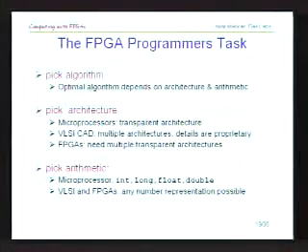You can have any number of bits for any variable, which is at first a little bit difficult to grasp, because you're used to having 16-bit integers, and we got used to thinking, well, we'll just pick whatever bit we need, and then we just have to go with it, because that's what my data path in my microprocessor is. There is no need to do that. You can actually specify any bit width and just have a compiler figure out how to build your architecture with the different bits that you have in your data representation.